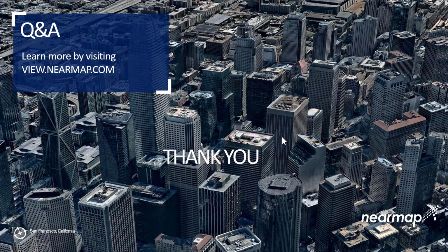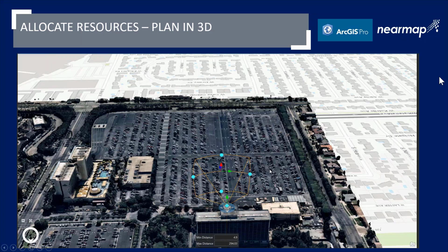So now I want to dive into a little bit of the use case and some examples of what we're going to be going over today, and then sort of the environment that they're going to be in. From our web hosted platform, there are a couple ways that you're able to leverage this type of data. This is an example of our customer-driven 3D export from our map browser. So what I've done is exported an area in SLPK format, scene layer package, so it can be dragged and dropped directly into ArcGIS Pro or hosted as a layer on ArcGIS Online if you want to have more collaboration on it.